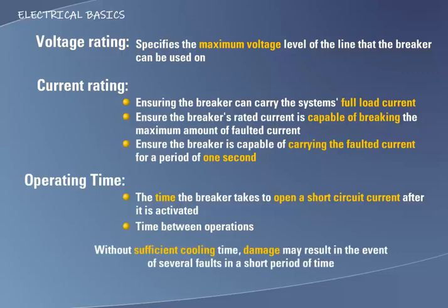Without being given cooling time, damage may result in the event of several faults occurring in a short period of time. If the cooling time of the breaker is not specified, standard cooling time is approximately 3 minutes for breakers not intended for rapid reclosing, and 0.3 seconds for breakers intended for automatic reclosing.